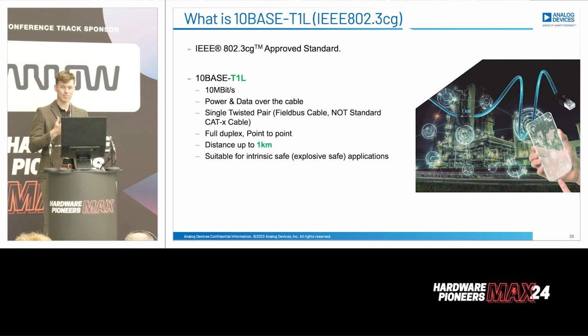It offers up to 1 kilometer, but the latest products will offer up to 1.7 kilometers in certain scenarios. It ranges from offering power of up to about 60 watts down to some of the intrinsically safe applications, which are around 500 milliwatts. So for those products that need to be certified by ATEX, this product will be able to give you that power and that data collection over a large scale.